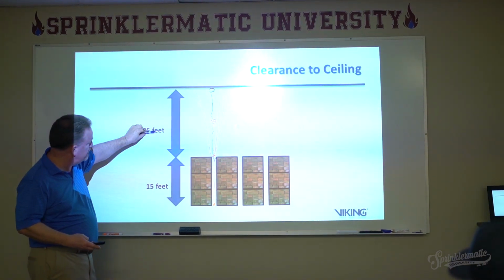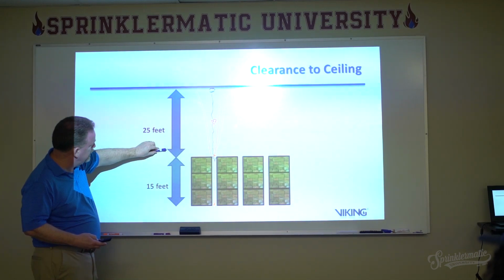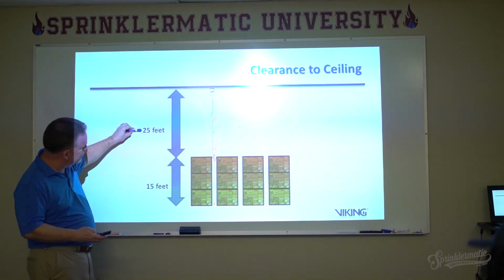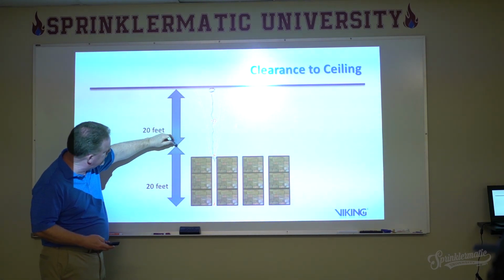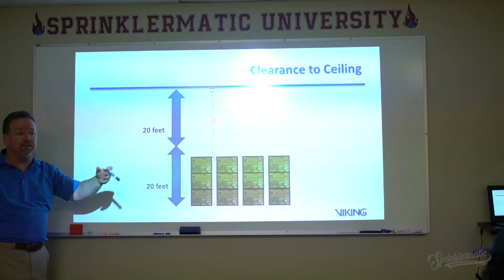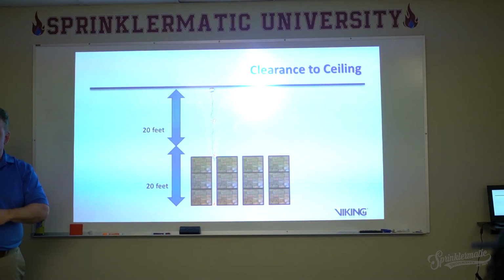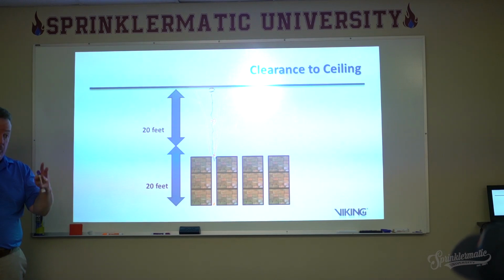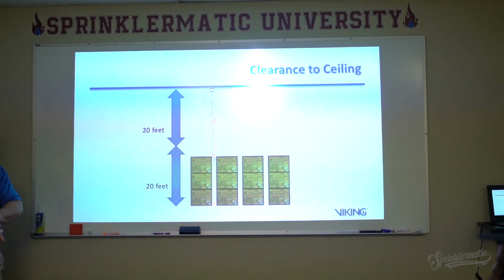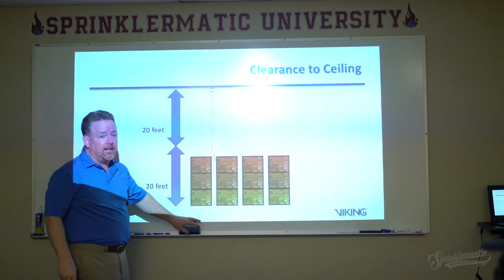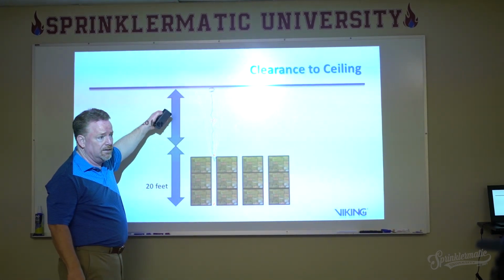25 feet? 25 feet here. So I would need to go up to 20 feet of storage. I would have to actually design this as though there were 20 feet of storage. Now that means something when we get into each of the chapters, okay? Because remember, the design of your storage sprinkler system is based on, one of the things it's based on, that storage height. So even though there's only 15 feet of storage, I have to treat it like it's 20 feet of storage in this case.